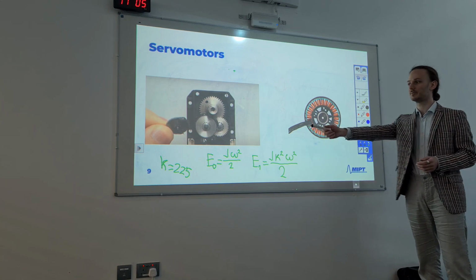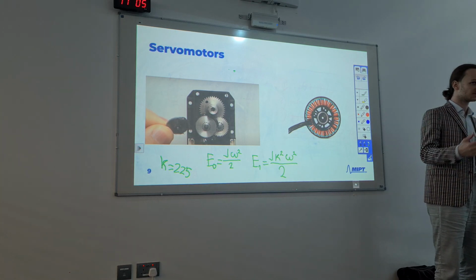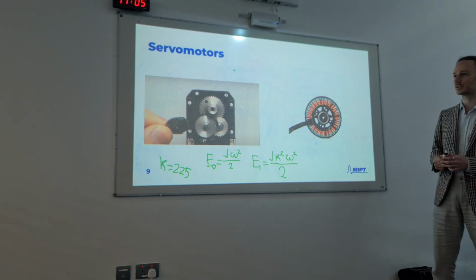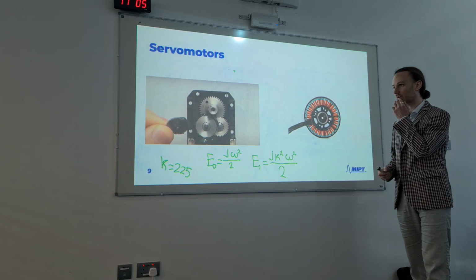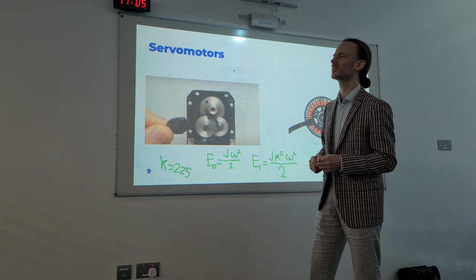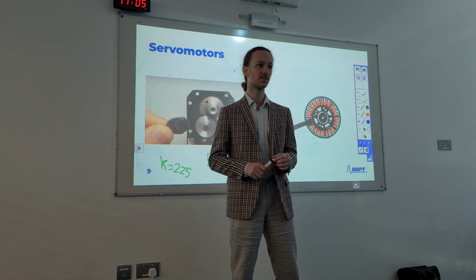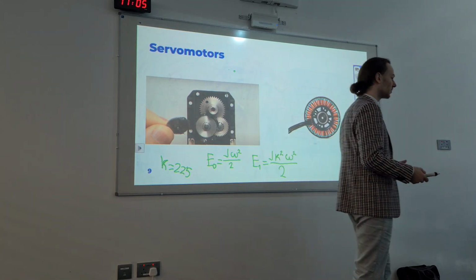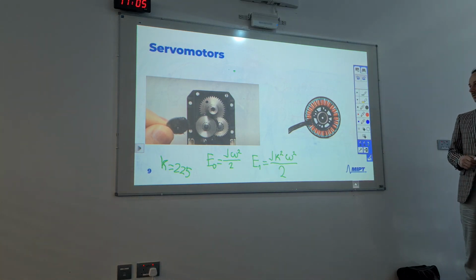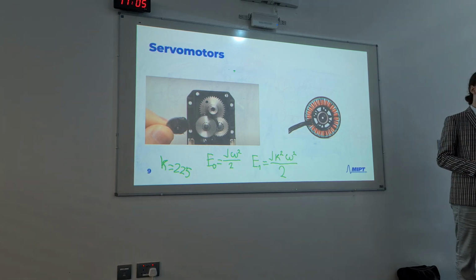And it could not really be fixed with programming. It's part of the mechanical construction. It's a property of these servo motors. They have a maximal angular acceleration of, I believe, approximately 2,000 degrees per second squared. So that's a limited value, and it's not infinitely high. That's why these robots are not running and not jumping.